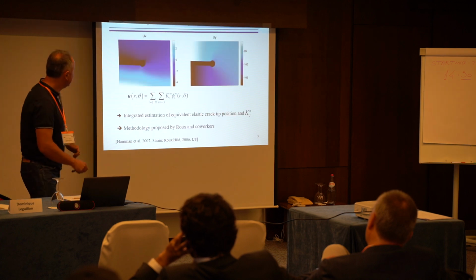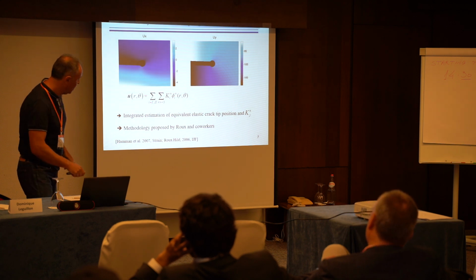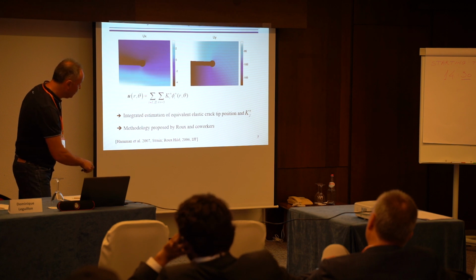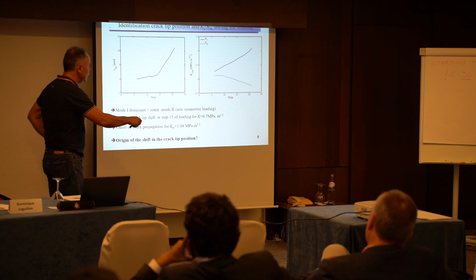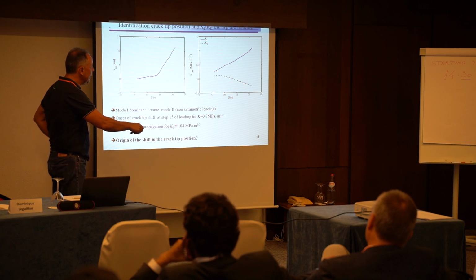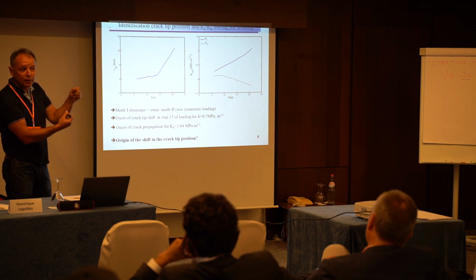But having this, you mask the non-reliable displacement field, you address this quantity, you invoke those papers, and you are able to measure the stress intensity factor under mode 1 and under mode 2. There is a little bit of mode 2 because of the loading conditions.